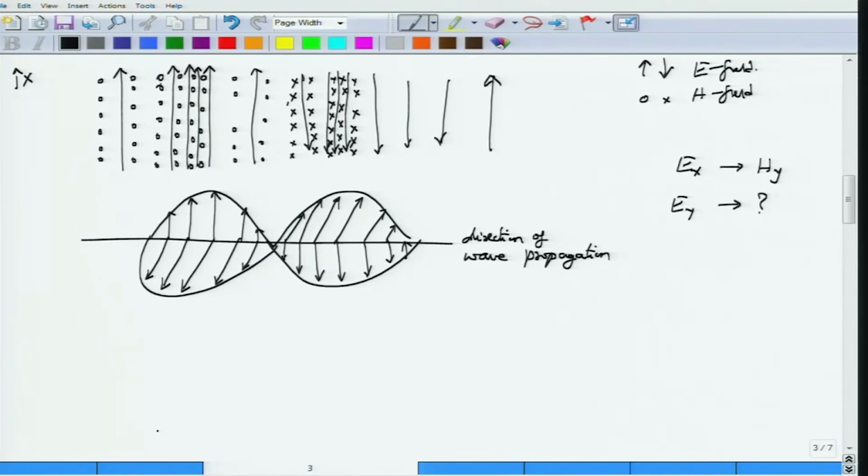And you will be right, you can begin with an Ey component and write down an expression by simplifying the Helmholtz equation. You will have to go back through the steps; I am not going to derive them here. I assume you can do this yourself after you look at the Helmholtz equation. But nevertheless, assuming that Ey is a function only of z and t, and with t we are assuming the form e to the power j omega t, we can drop that particular term.